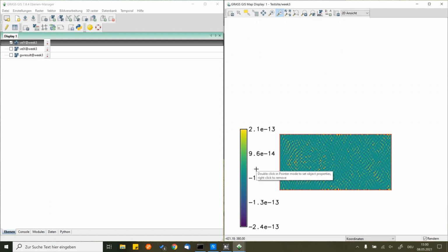So as this always emphasizes, numerical methods are approximations. So there is nothing like a specific zero, right? There is some oscillation around zero, but you see, it's 10 to the minus 14 meters per second, which is really, really, really slow. So it is, in a numerical sense, zero. But now you already have a feeling for what kind of numerical noise, with this setup and this spatial resolution, GRASS GIS has, an accuracy based on the numerical method behind it.